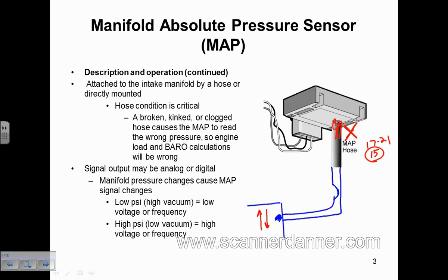How much pressure's up there? None. So how much fuel are you getting? None. So when you let off the throttle and come back to an idle, the car won't run. You crank it over, keep cranking it, it's still basing the entire fuel curve off of that 35,000 feet of elevation. How do we reset it?